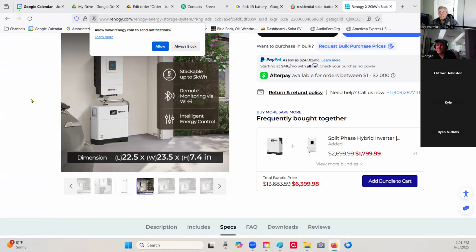So this is one reason we're going into lithium ion. I said lead acid. Yeah, lead acid batteries were not practical for anything but very small systems. Lithium ion, they're cheaper now. They're more energy dense, which means you get more power for less weight, less volume, and it's just a better system. So this is one of the reasons now, the advent of lithium ion batteries. One reason 50% of all the installations now incorporate batteries, because it's economical to do so.